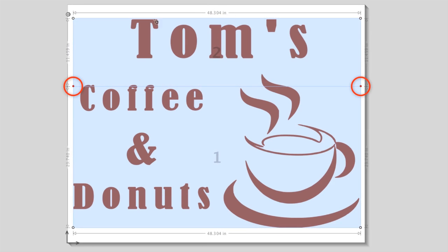The red grab handles are used to adjust the tiles within the pattern. For instance, we can adjust the tile so that the tile doesn't split the middle of an object. Here we can raise the line just a hair to make the split occur between the objects.